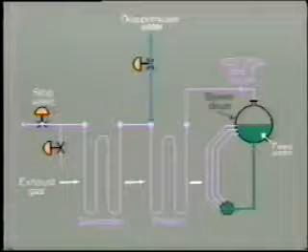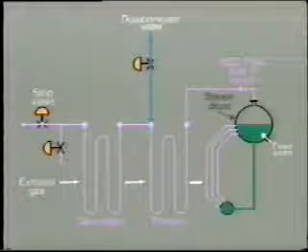On large HRSGs, the superheater is usually divided into two sections, primary and secondary, with headers between them. The secondary section produces the higher temperature steam because it is located upstream in the higher temperature gas zone. We can control the temperature of the steam leaving the unit by spraying in a small quantity of feed water into the steam through a de-superheater at the primary outlet header.